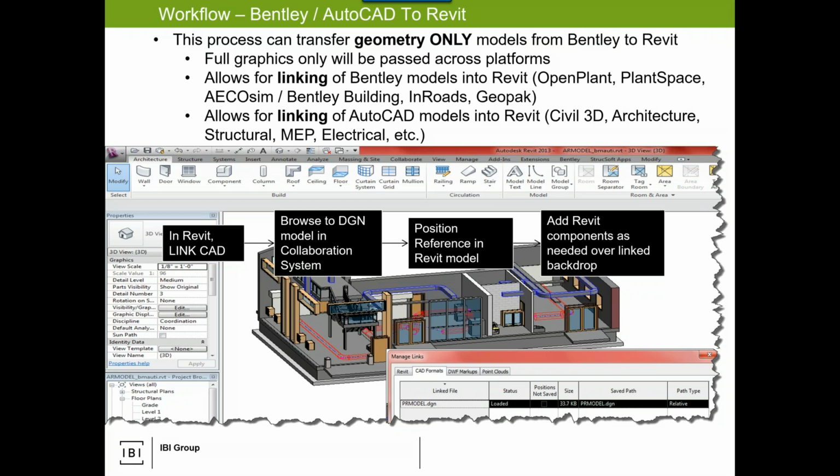The specs are all in Bentley. Nothing is in Revit that team wants to use. I can still have it be intelligent. Then I can pull it all into Navisworks or Navigator if I wanted to do formal clash detections and stuff. But in the world of Revit, at least I have the backdrop for me to model. So I'm not placing, I don't know, my door, or I have enough clearance around my columns in order to move to get to the bottom, to the stairs and everything. So these things are doable even if it involves a workflow in a system.